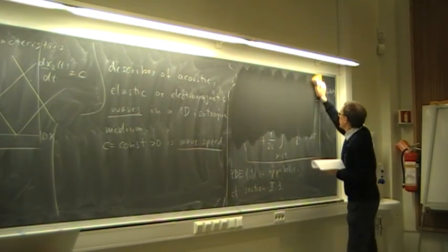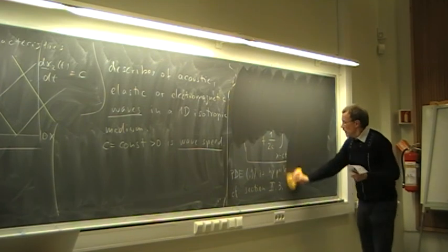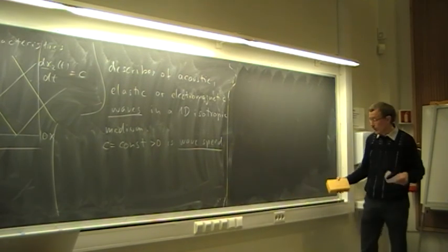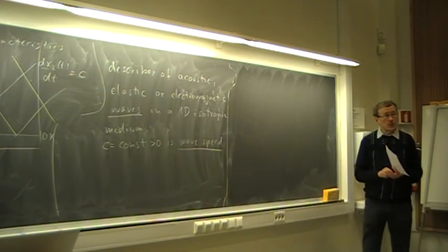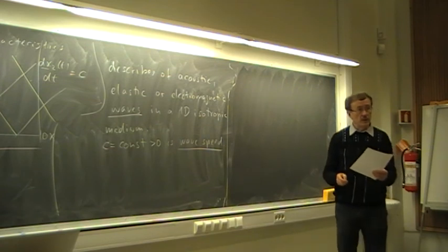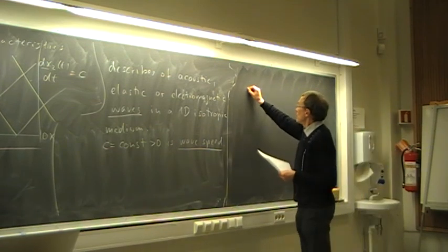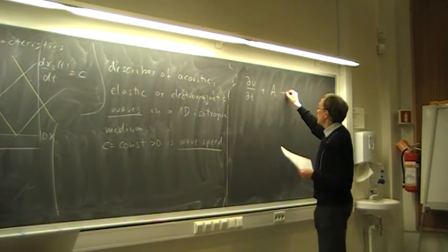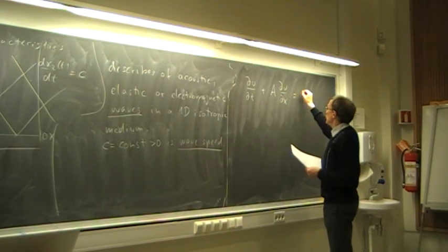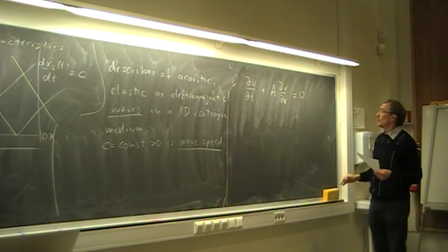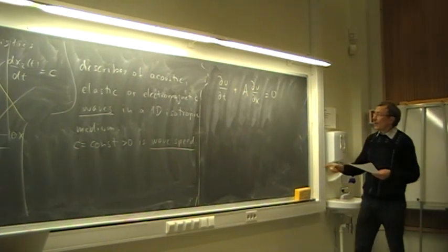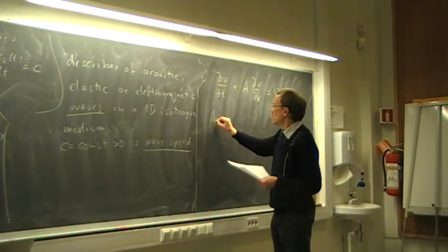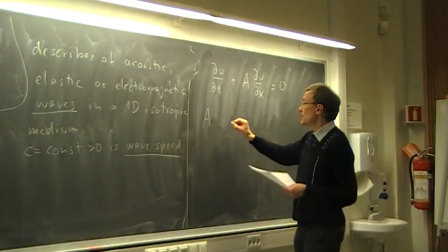There is more theory to that, but we should not go into detail on that. That will be part of a follow-up course, TP 4165, computational heat and fluid flow. You can write this equation in the form A du/dx equal to 0, or say with a zeroth or constant term, where A is a coefficient matrix that must have real eigenvalues.